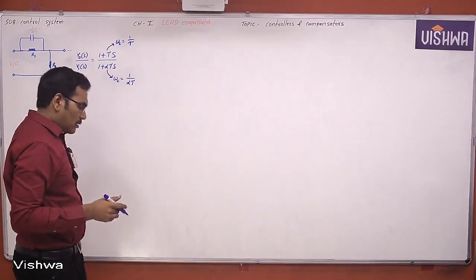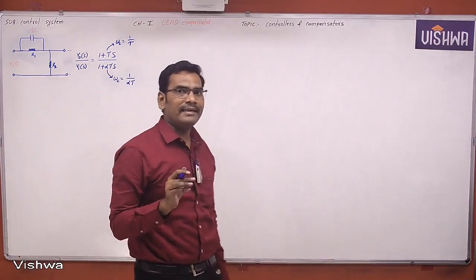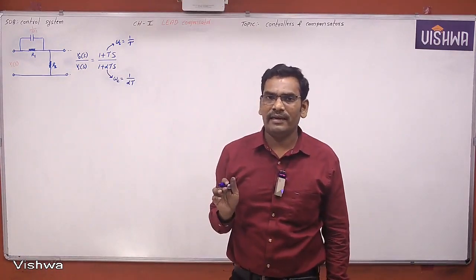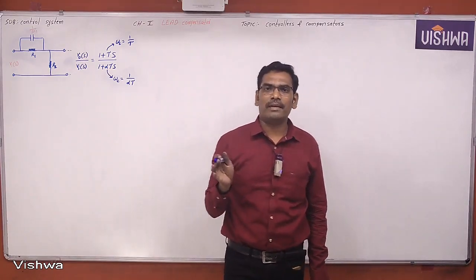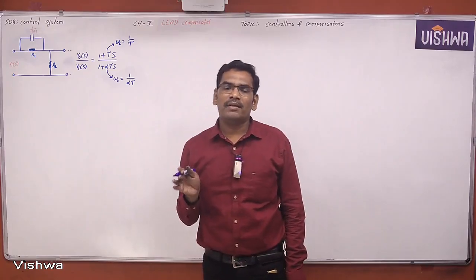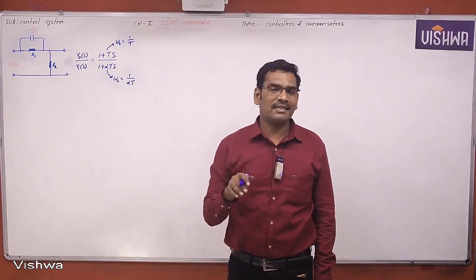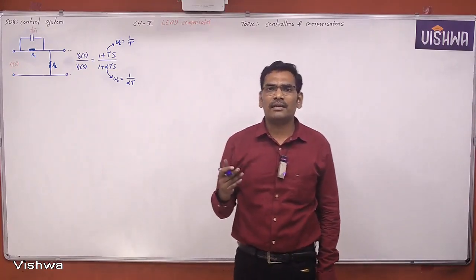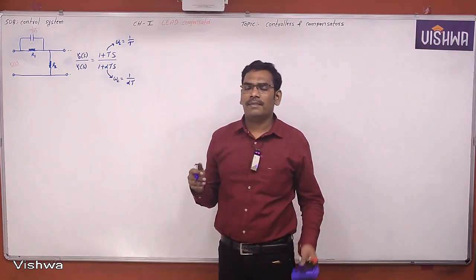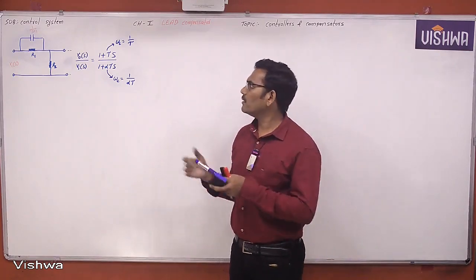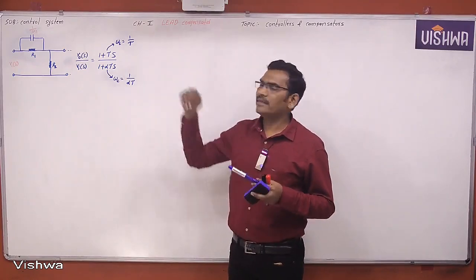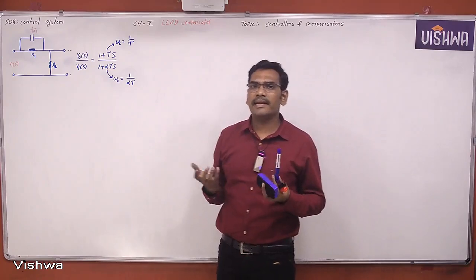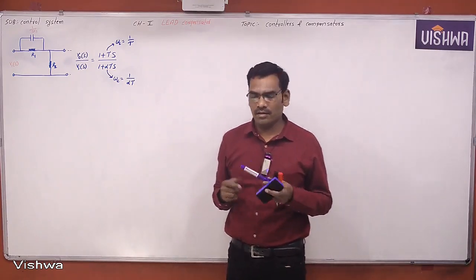So then, is this compensator a lead compensator or not? We want to identify that. You have already a frequency response plot called the Bode plot, polar plot, Nyquist plot. But the Bode plot uses the phase characteristics directly. So phase versus frequency response is already available. You draw the phase versus frequency response, which is nothing but the Bode phase plot. For this particular compensator, you can easily identify whether it is a lead compensator or not.